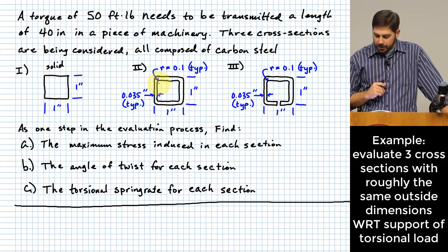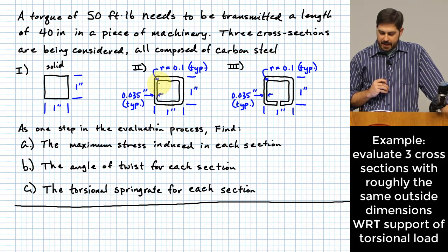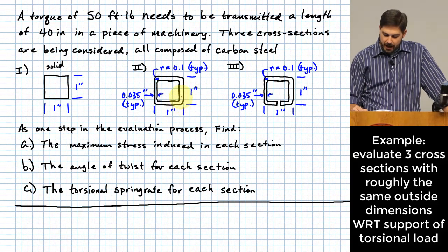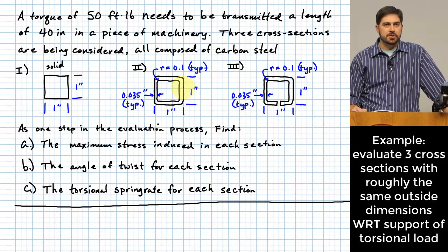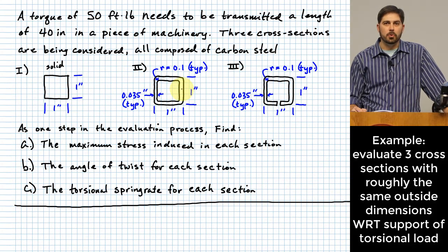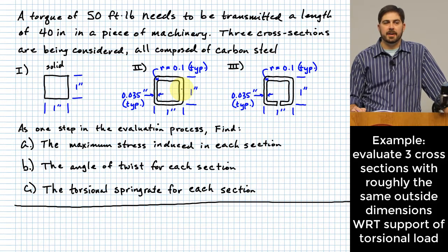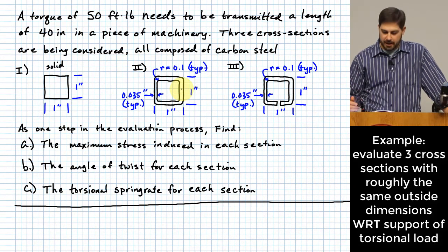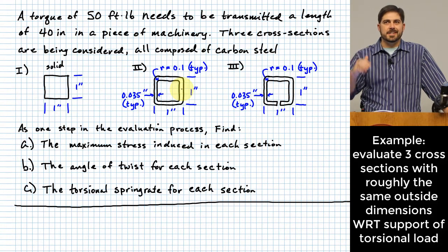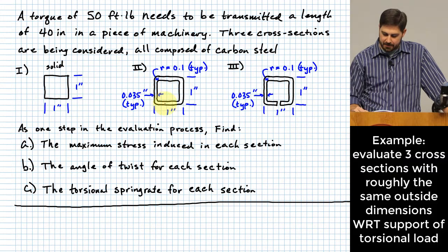One little comment I'll make on that is that if the corners are rounded, that is actually beneficial to the carrying of torsion in these members. If they have really sharp corners, that shearing flow that I talked about a minute ago doesn't happen quite as efficiently around those corners. So it helps a little bit to have these slightly rounded corners.